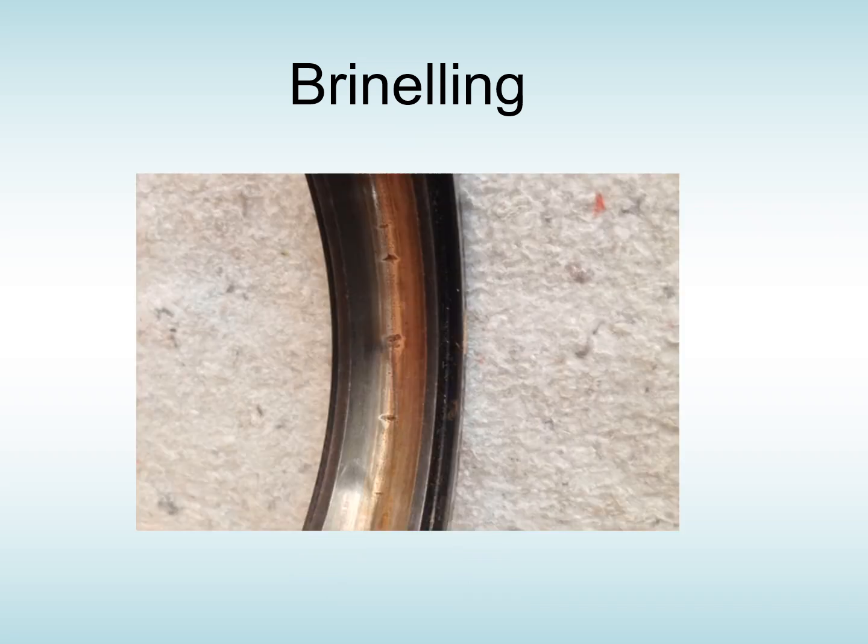The result is you're going to end up with pitting like this, and it's going to greatly reduce the lifespan of that bearing. So what you need to do is, if you've got something large, turn it over every now and again and not let it sit in the same position.